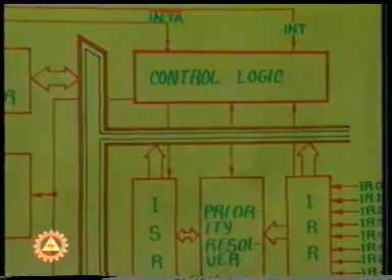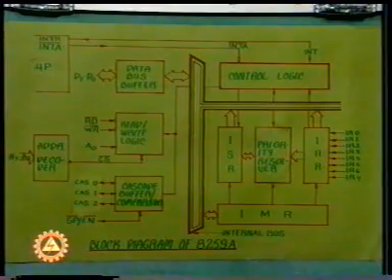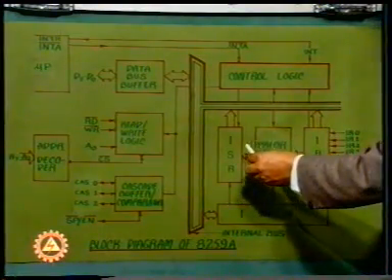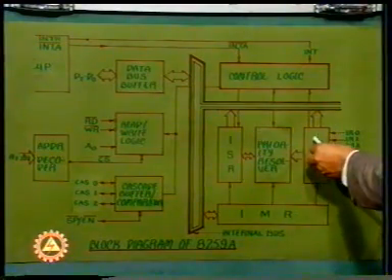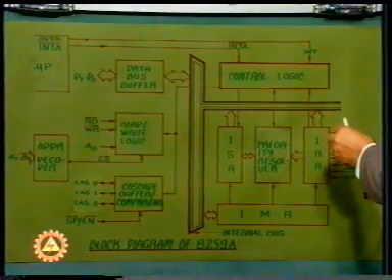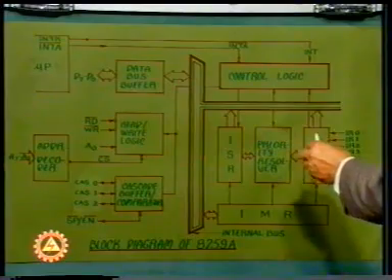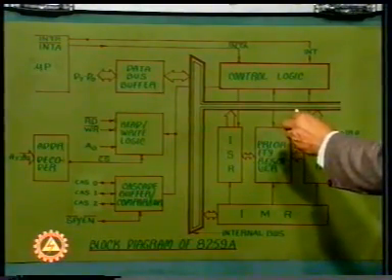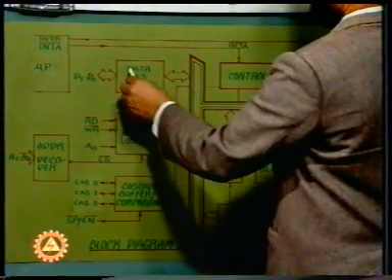On receiving this acknowledgement, the controller sets the corresponding bit of the interrupt in the in-service register and resets the corresponding bit in the IRR, thereby marking the beginning of the service of the interrupt. Simultaneously, it sends the operation code of the call instruction to the system through the data bus buffer.